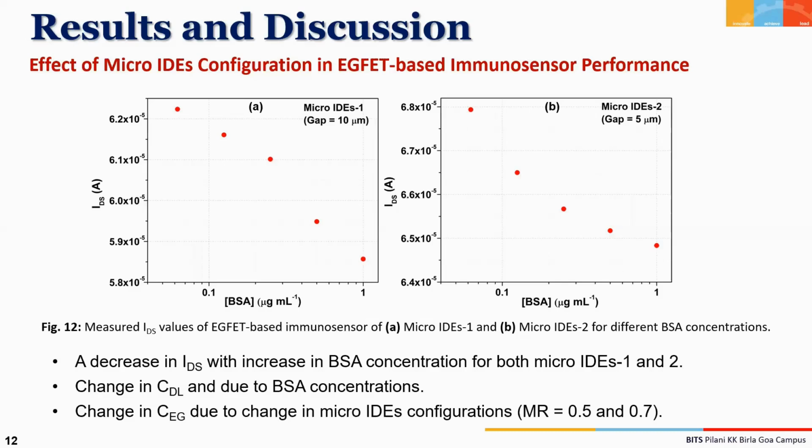We have also separately investigated different geometrical configurations, where we found that the gap can be reduced, but there is some limitation as well, because there will be an effect of crosstalk and other things. So we have already investigated what should be the optimum metal ratio for higher measurement sensitivity. Here also we validated that the higher 0.7 metallization ratio will give better measurement sensitivity than the other.